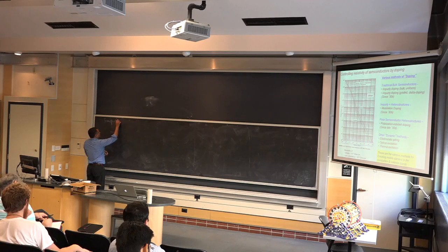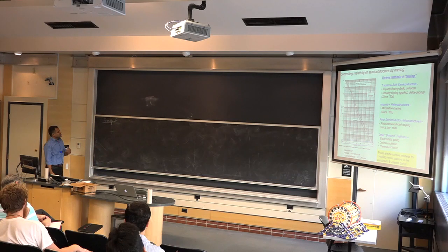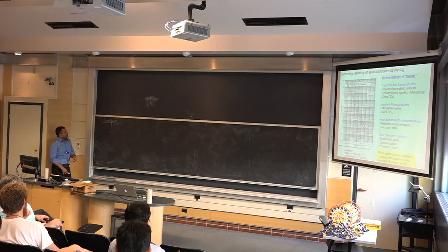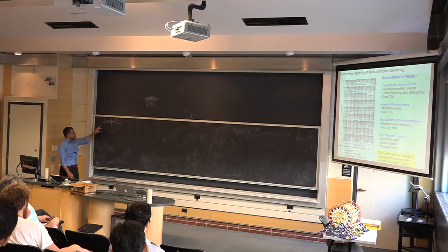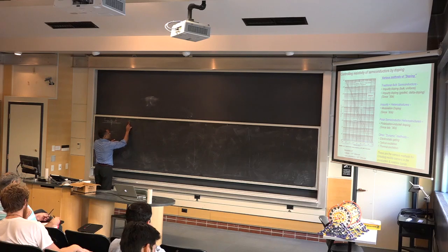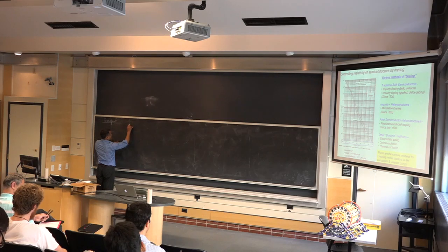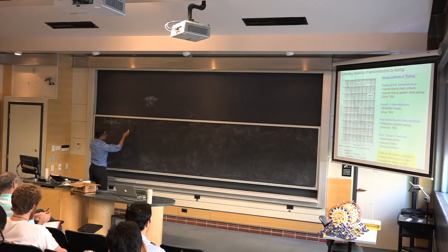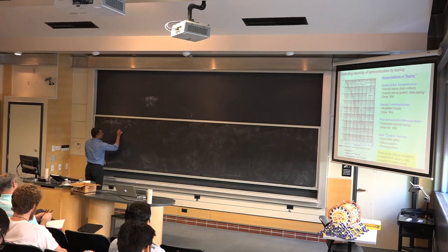So, transport. Okay? And there are many levels of it, and as I mentioned just now, there'll be a whole course next semester on it. But right now I'm going to summarize most of the semiconductor transport that we will need in this course in one equation. That's what's called the drift-diffusion equation. So I'm going to write J, the current density, and I'm going to show you some pictures of where it comes from. Let's say due to electrons, and there will be an equivalent equation for holes. This is the current density.